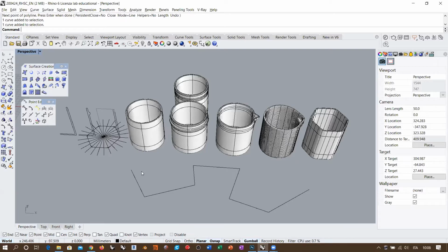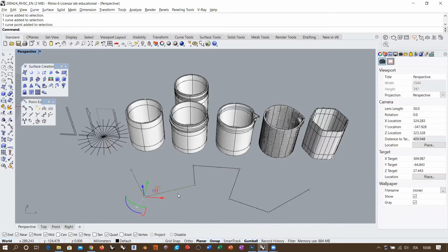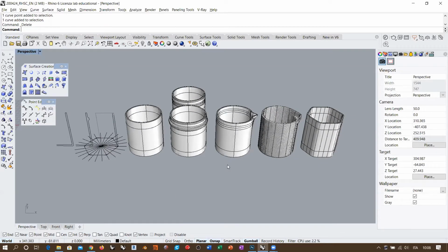So in that case, each knot produces a kink, which is a vertex. So in the polyline, these discontinuities are at the same time control points, and they are also knots, and they are kinks, okay? So the polyline is an extremely particular NURBS curve because of this particular situation, okay? As for the rest, there is no particular geometry that by default has this kind of weird behavior.